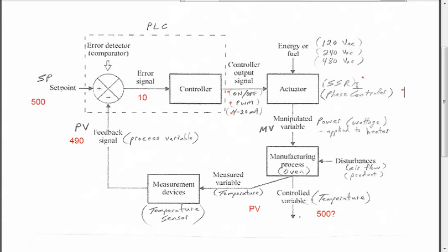So that's on-off control, but with solid-state relays, you could also turn it on for a certain amount of time and turn it off for a certain amount of time. If it's a slow responding system, you might have a large oven and just time proportion for heat control, such as how many seconds is it on and how many seconds is it off.